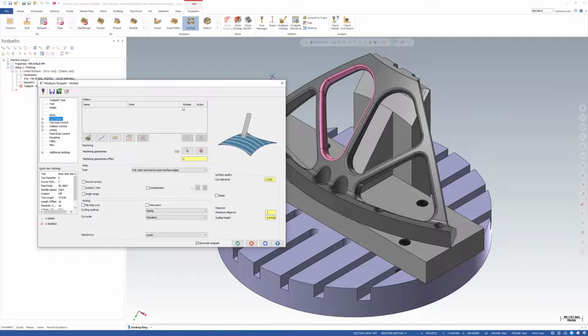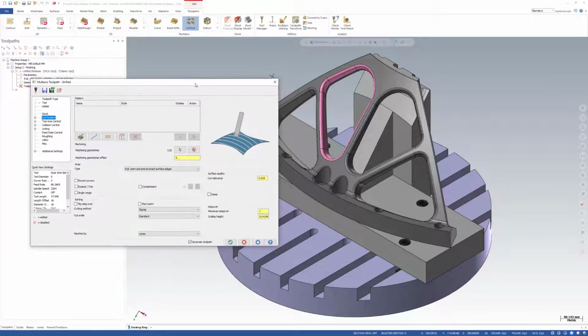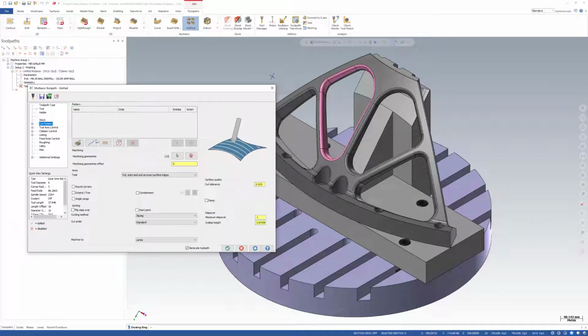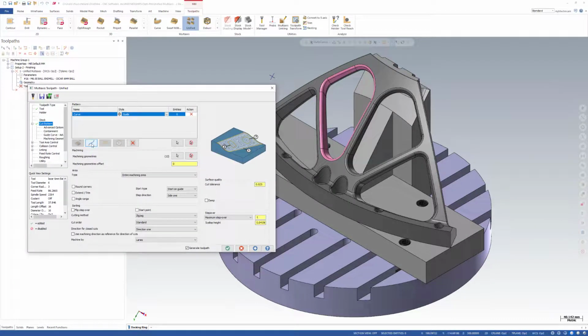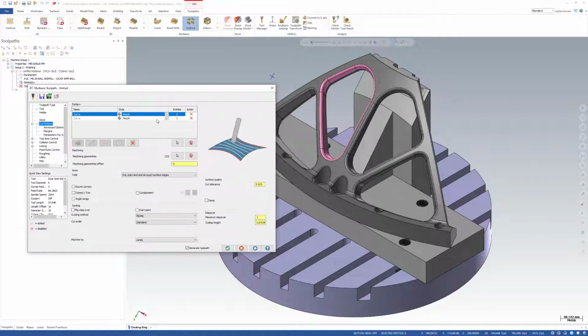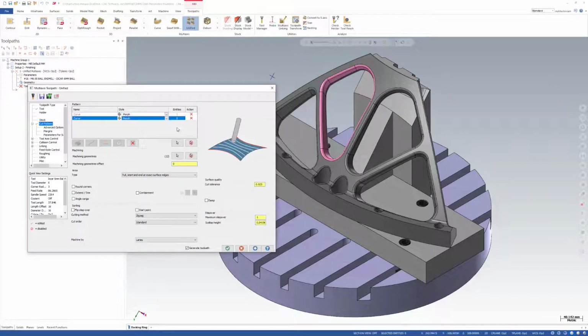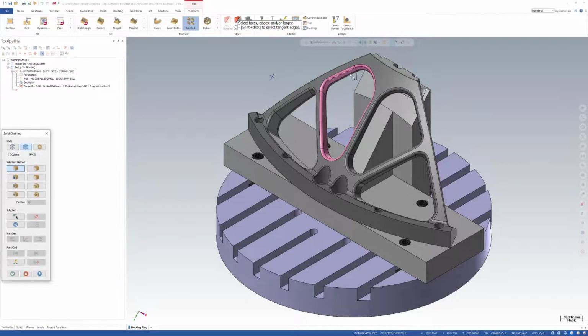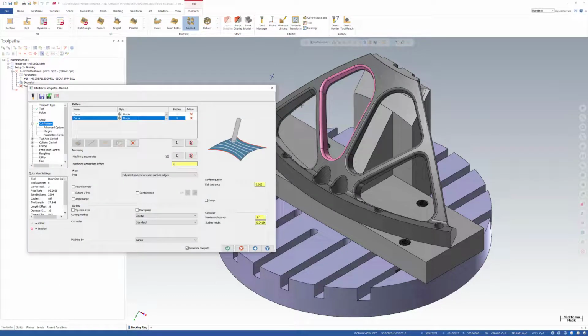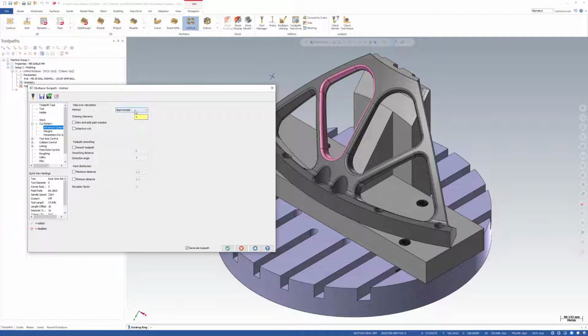Select all that. And to create a morph toolpath, we have always had to select 2 separate curves, a to curve and a from curve. So let's select 2 curve inputs and change these to morph. So for the first one, it will be our from curve. So I'll shift click this. Our second one, shift click there. So we have the input for a morph toolpath. Same as everything you've seen before, right?